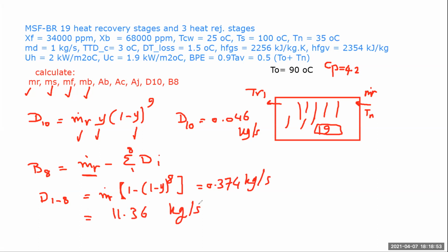So far, what has been a trick that has not been used in this example is something related to the utilization of the overall balance. For example, this example did not ask for how much is m dot of the cooling water. If this had been asked, then you could have looked at the whole power plant or the whole desalination plant as your control volume.